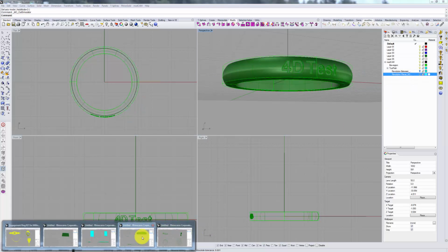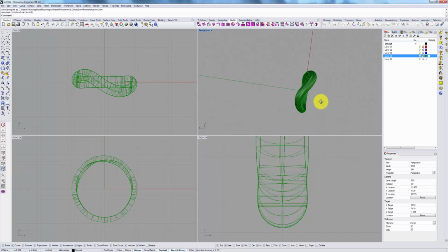Finally, we have our 5-axis simultaneous movement for more complex things, like this ring. So the reason why we might want to use a 5-axis simultaneous strategy on this particular ring rather than a rotary is because the rotary keeps its x and y movement similar as it rotates.